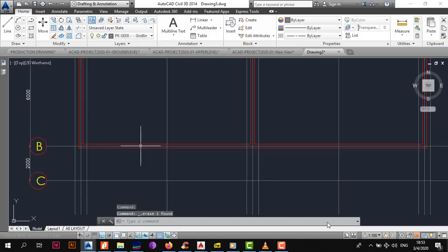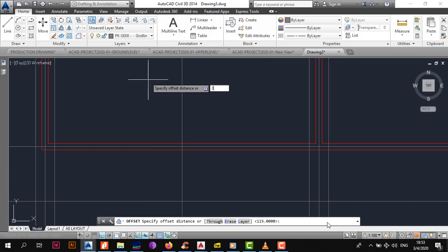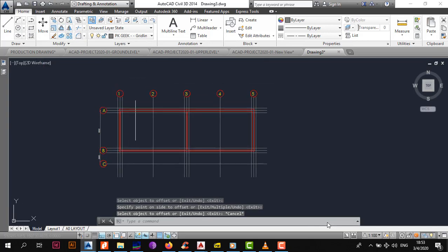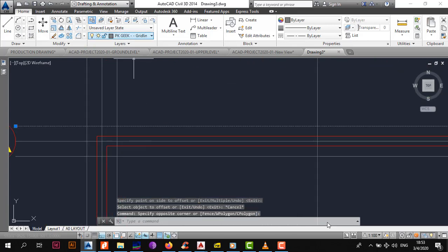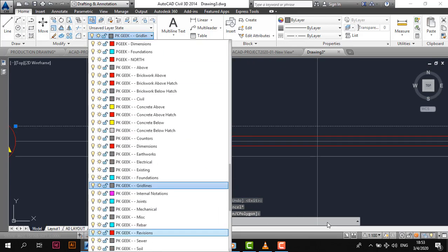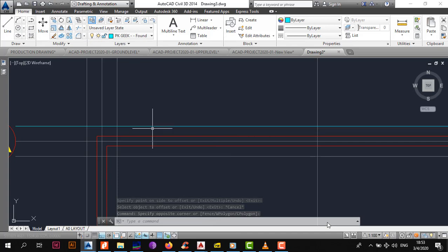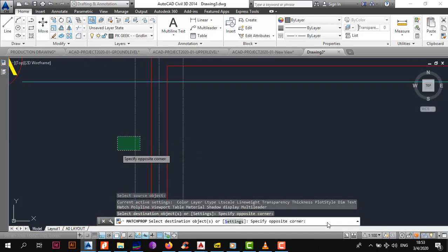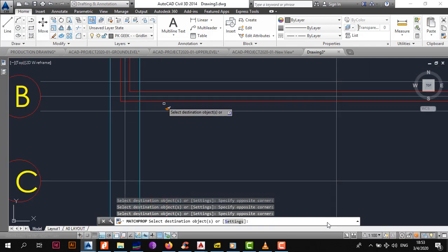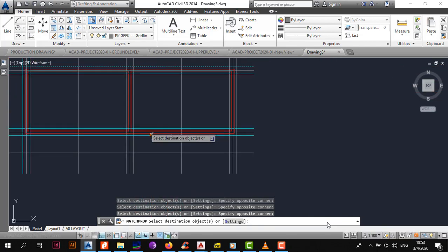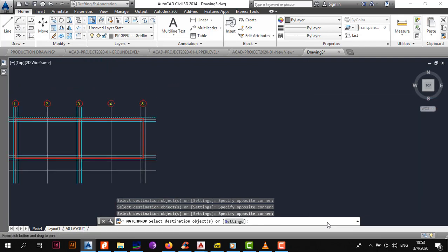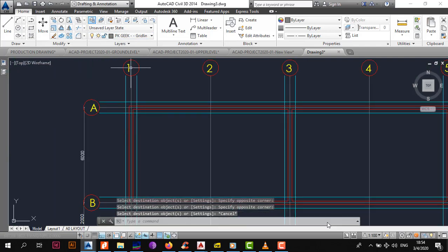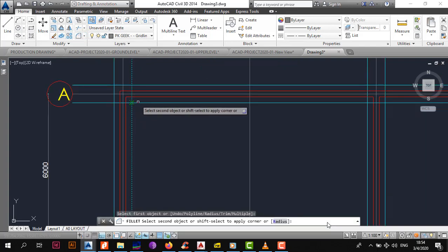Then we need to remove these ones because the trenches are going to be there, so we're just going to offset this by 350 since we're trying to make trenches. Right, and then the cool thing about this, you want to make your trenches, I have a foundation layout. There we go. So remember, your trenches are 700 wide. There you go. This is okay. Right, so we got music in the background and we're just making the trenches 700.